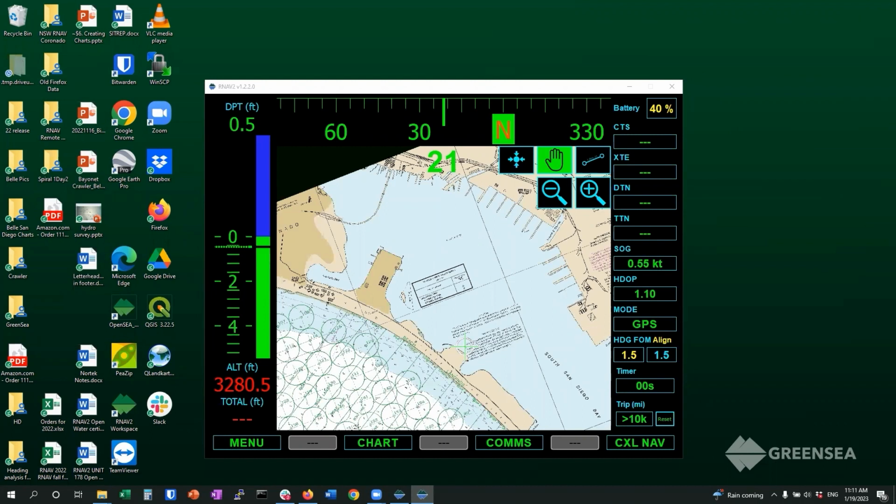In today's how-to video, we're going to cover logging. We're going to cover how you actually apply the application, why we generally would do it, and some of the outputs that it provides. So logging is nothing more than a recorded file that's provided on the RNAV when logging is turned on. This can provide a few different outputs. It'll provide a sonar view if you had sonar plugged in. You can do an actual MP4 playback to see if you had an obstacle. It also provides the unique file that we're going to be talking about later on, which is the telemetry file.